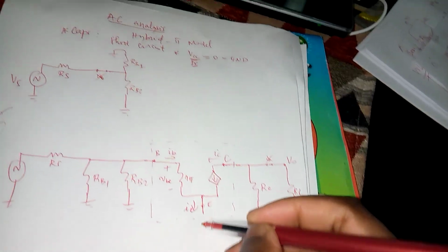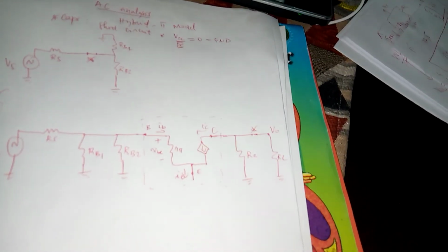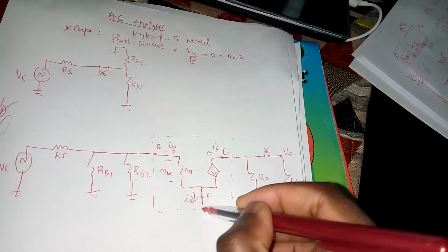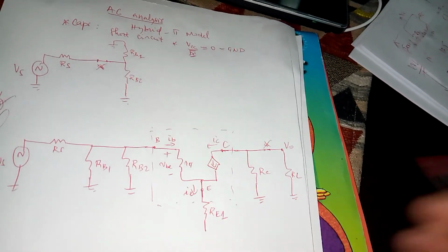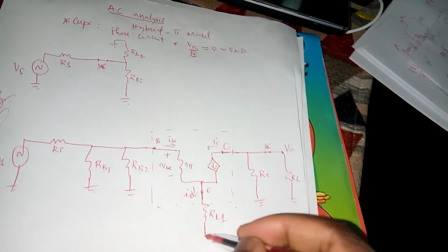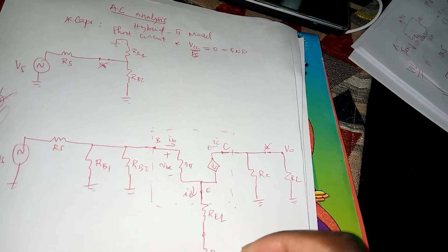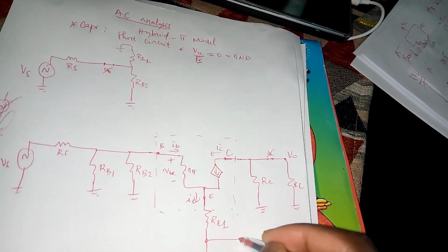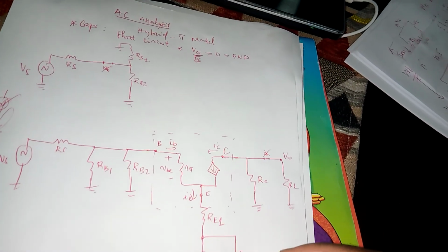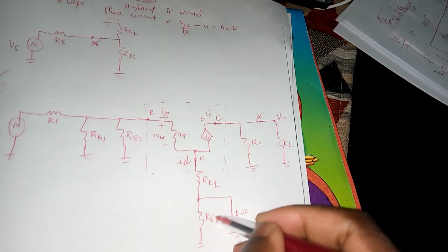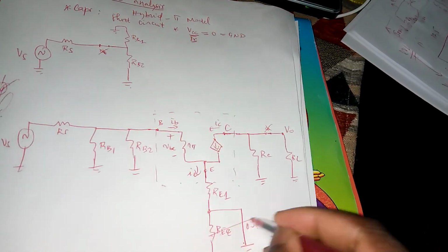On the emitter side, CE becomes a short circuit. But before CE, we go through RE1 first. When we reach the point where RE2 is, we have RE2 to ground, but also CE, which has become a short circuit in AC, all the way to ground. Now you've got 0 ohm in parallel with RE2. 0 ohm in parallel with anything gives 0 ohms.